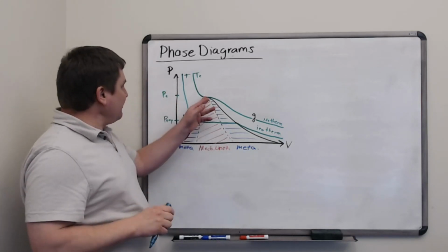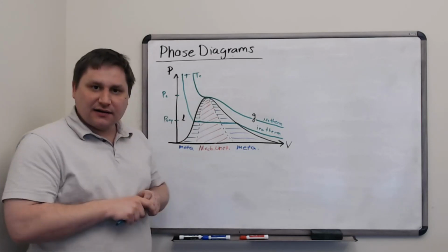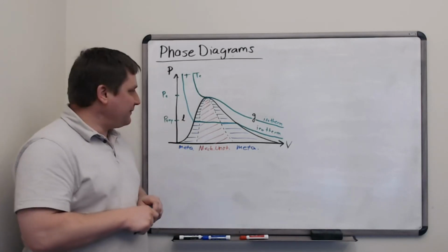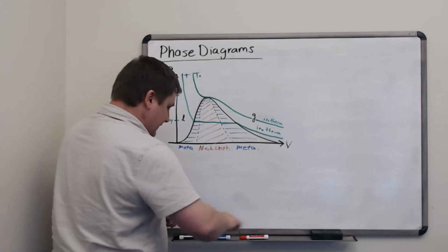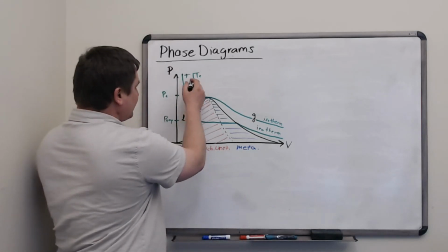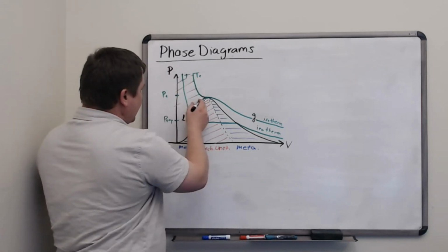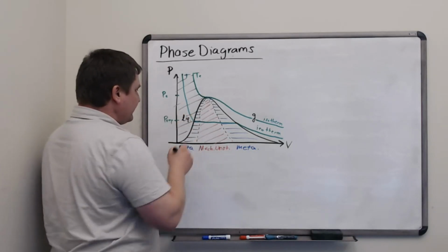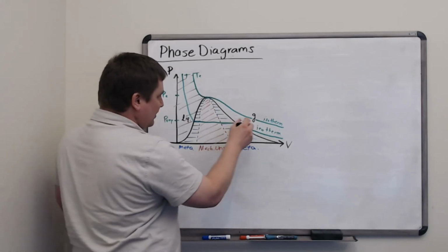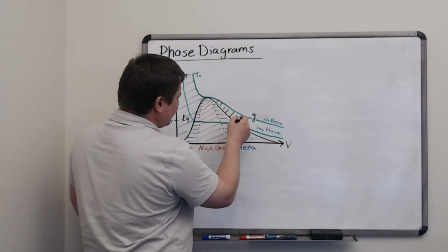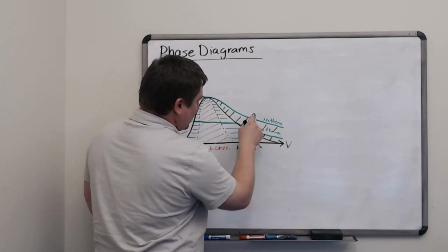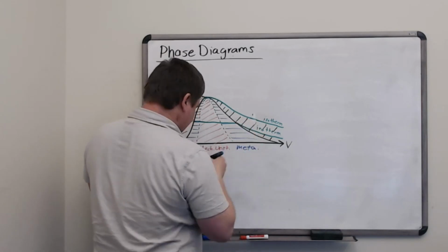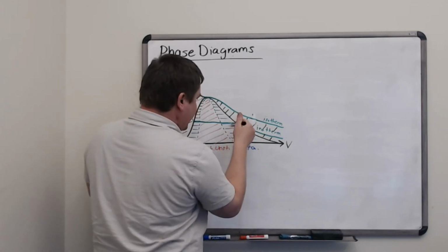So just at the critical pressure here, it has a zero slope, but then it goes up and starts looking maybe more like a liquid. So anything really that's below this critical isotherm and to the left of the mixture envelope is clearly a liquid. And anything that is below this critical isotherm and on the right side of the envelope is clearly a gas.